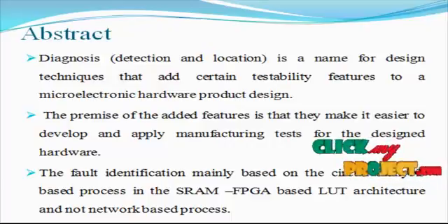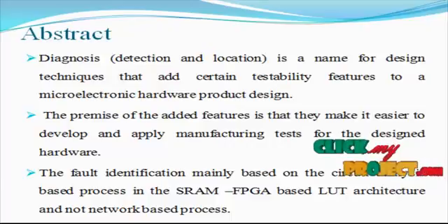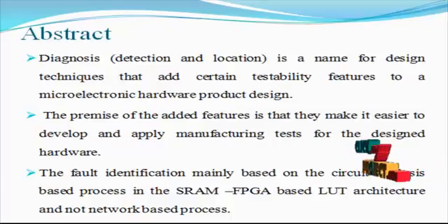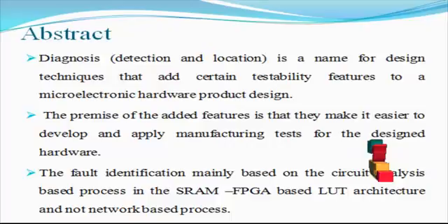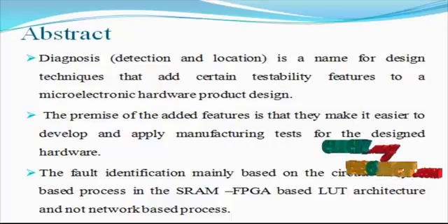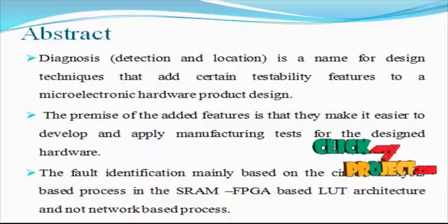Net appropriate grouping is accomplished by utilizing features such as the presence of paths of nets that are either disjoint or joint between the primary input and at least one primary output. As validated by simulation of a variety of benchmark circuits, these methods scale the fault identification, detecting and locating faults based on the diagnosis methodology.